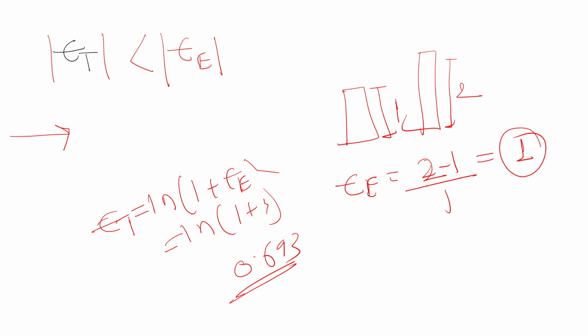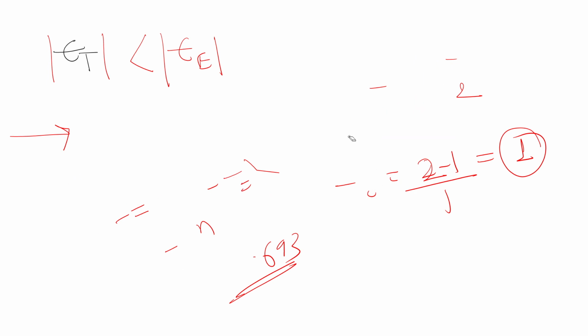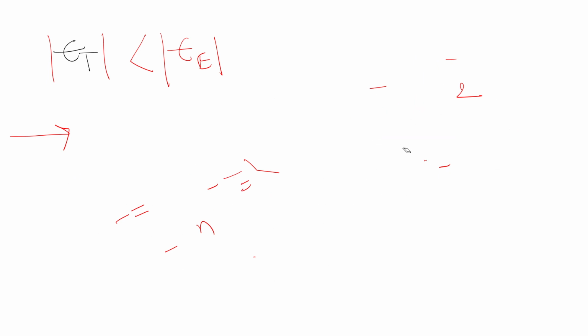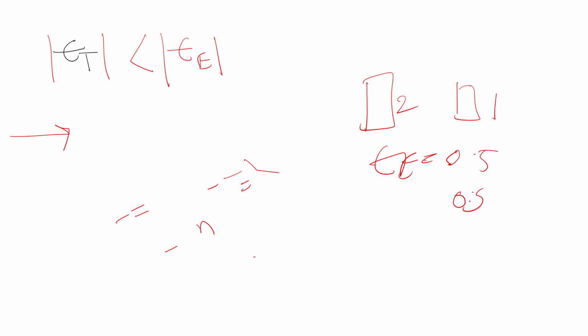But if you do the strain in compression, I'll rub it, from 2 to 1, then your engineering strain value is minus 0.5, and the magnitude is 0.5 only.